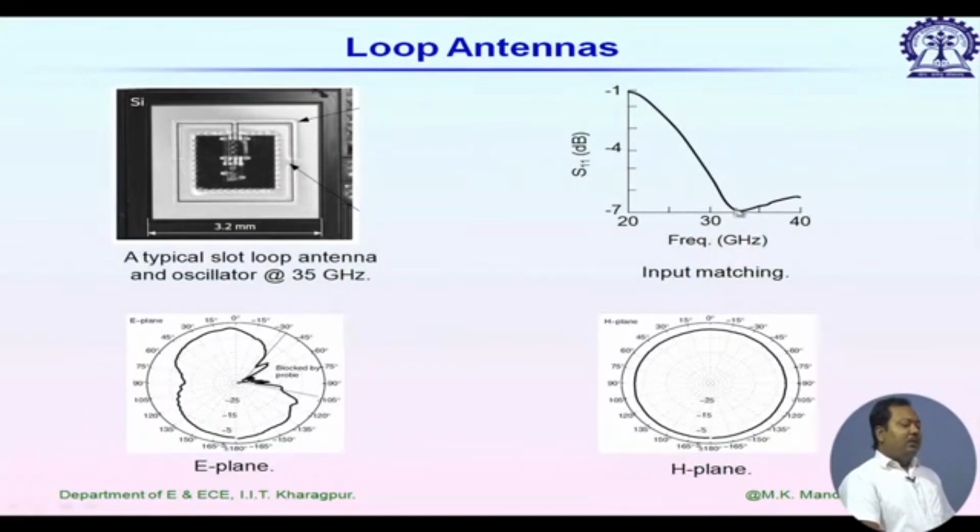Its bandwidth is quite high. Here you see we can't even achieve minus 10 dB of input impedance matching, but for handheld device application sometimes 3 dB bandwidth is enough. Here they are considering 3 dB matching bandwidth, and it is quite wide due to the ground plane resonance.